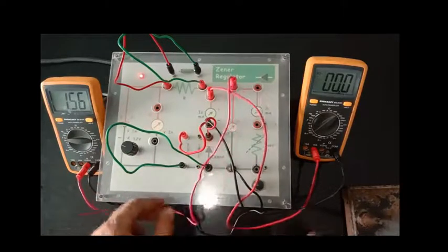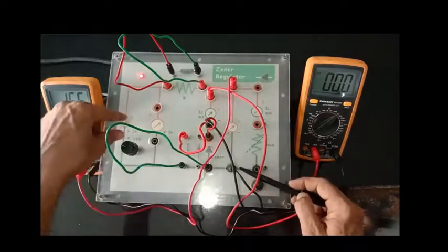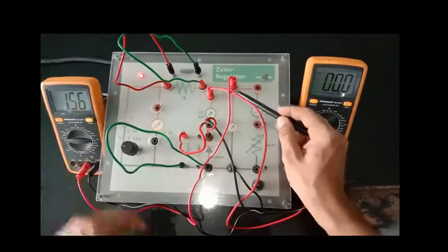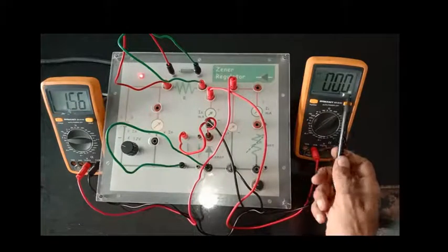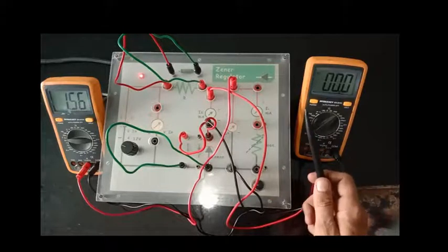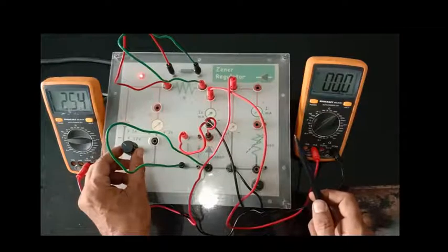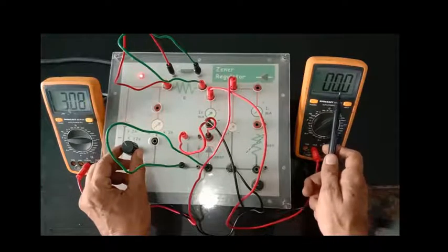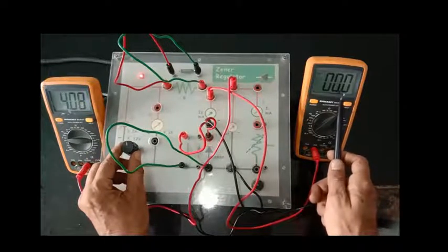Now if you are connecting the input voltage and giving a certain voltage, the same voltage you can measure as an output voltage, but current is still zero. That means the Zener is not yet triggered, it is still in cutoff mode. Now you have to increase the voltage till you notice the very first pulse of current which is passing through the Zener, that is IZ.